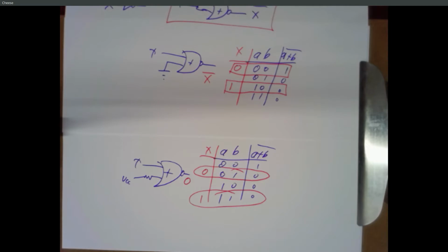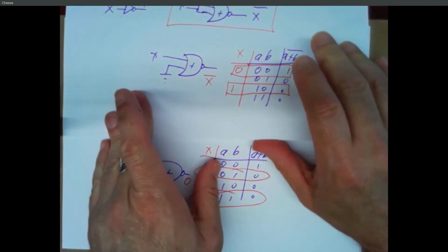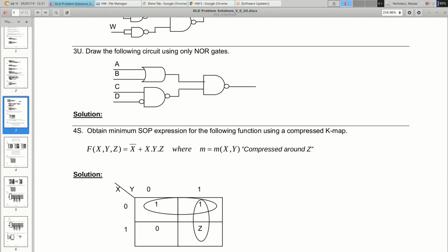You actually do it with the C and D inputs. So what about C and D? So you're clear how to make an inverter out of a NOR gate, right? And we know how to make an OR gate. It's just a NOR gate with another inverter. So C and D are different because they're going into an AND gate. And there's this funny bubble in the beginning and a bubble on the end.